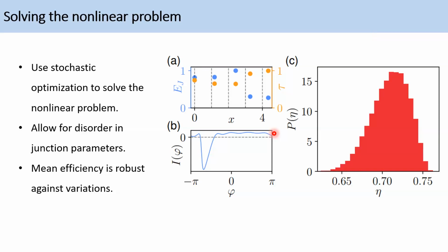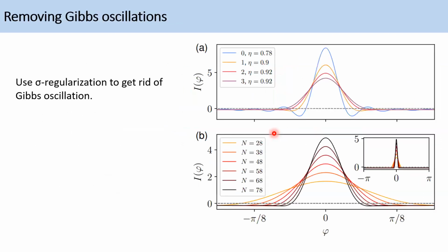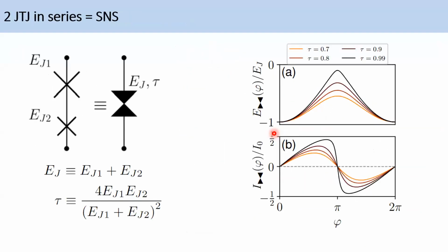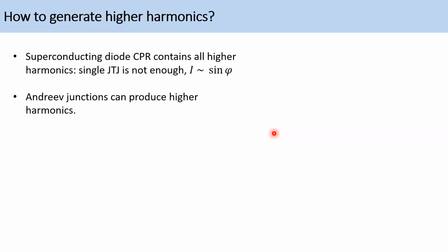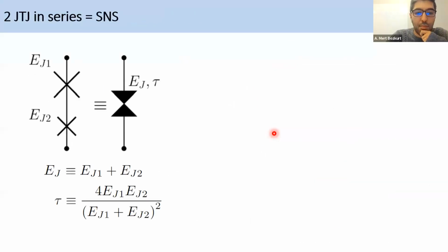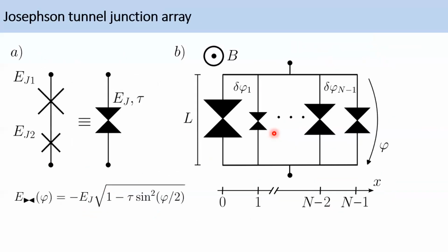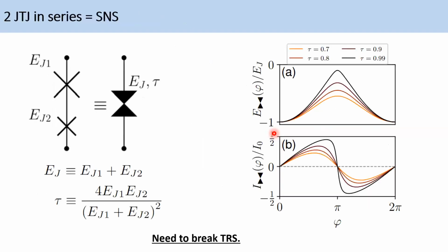Okay, I see. Yes. So in principle, there would probably also be some co-evolution, right? Where you would engineer a device and do some spectroscopy to see what the EJ and JMs are, and then engineer based on this what next Josephson junction you need. Then you need to characterize what this is, right?